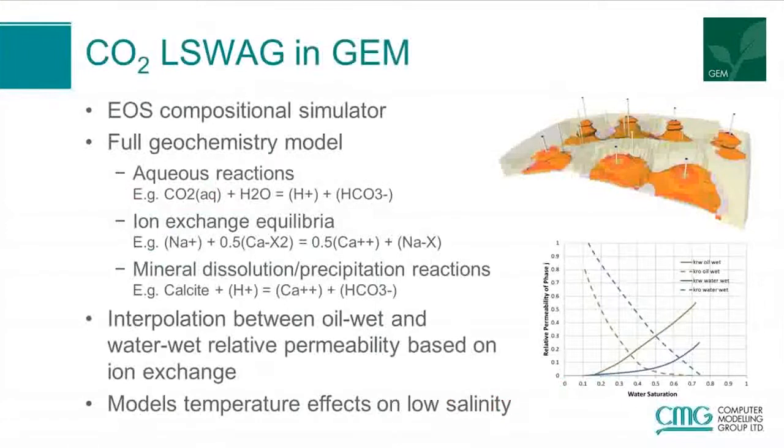In GEM, we can capture all the mechanisms involved in the carbon dioxide low salinity WAG processes. We have an equation of state compositional simulator that can capture all the miscibility mechanisms involved in carbon dioxide injection. And we also have a full geochemistry model to simulate the aqueous reactions, ion exchange equilibria, and the mineral dissolution and precipitation reactions occurring during low salinity water injection.